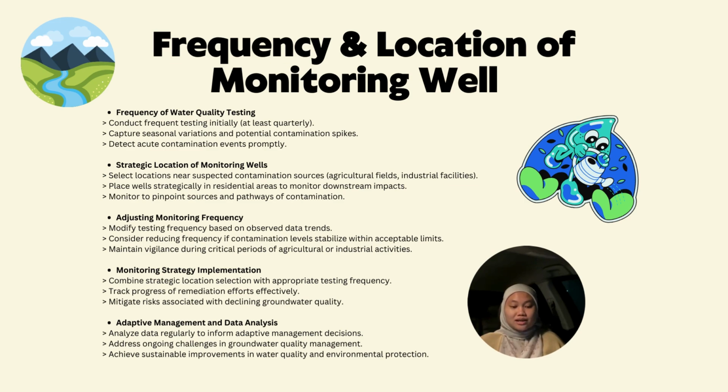So the last slide, which is the frequency and location of monitoring wells, starting with the frequency of water quality testing. Conduct frequent testing initially. Capture seasonal variation and potential contamination spikes. Detect acute contamination events promptly.